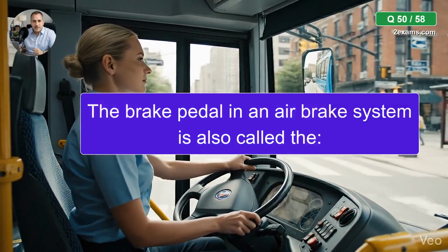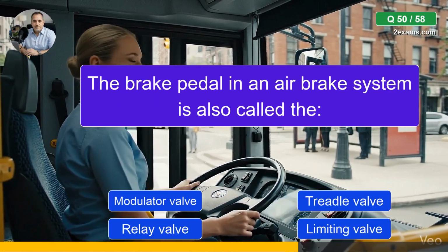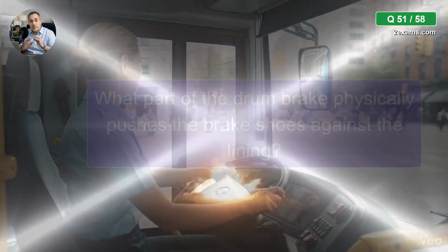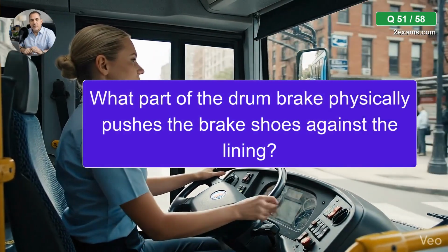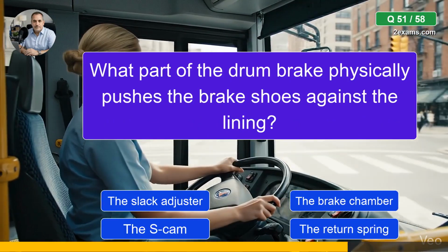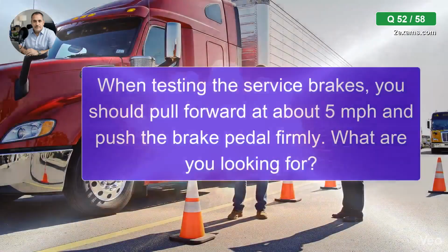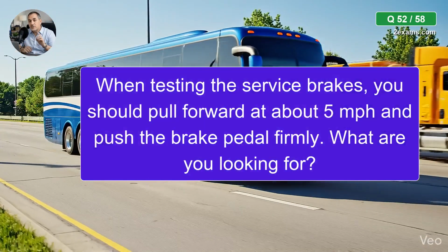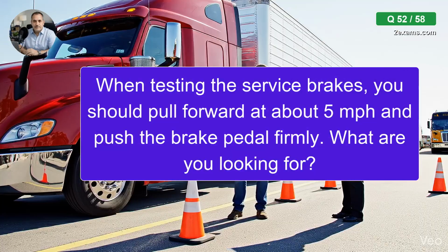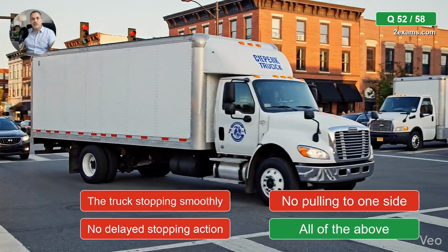The brake pedal in an air brake system is also called the treadle valve. What part of the drum brake physically pushes the brake shoes against the lining? The correct answer is, the S-cam. When testing the service brakes, you should pull forward at about 5 miles per hour and push the brake pedal firmly. What are you looking for? The correct answer is, all of the above.